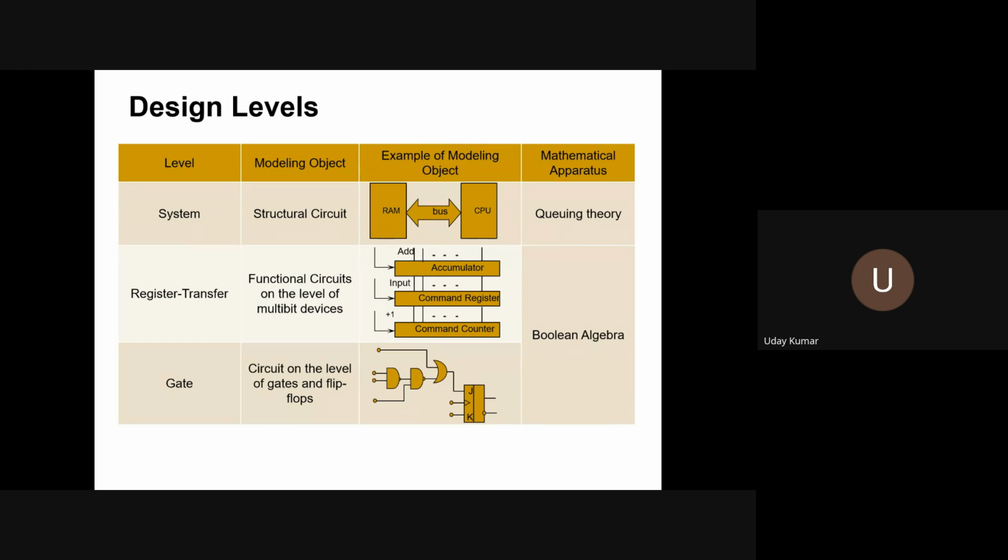So that's how the architect starts, and then the register transfer level. Once the architecture is defined, no code is written from scratch. Predefined modules will be there. They'll be integrating all the modules, and we'll have the register transfer level code written by the front-end designers after the architecture is given by the top level architect. And here, all the sequences, functions, and logics will be written. There will be, as we all know, behavioral, gate level, and data flow level modeling.